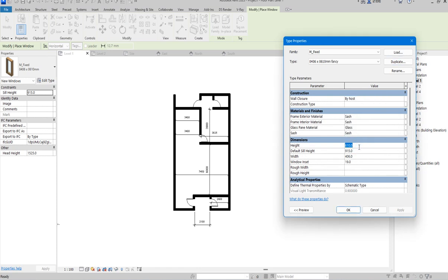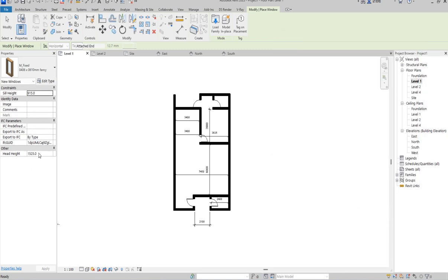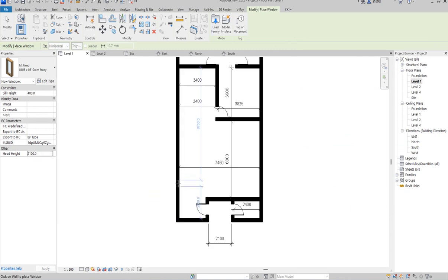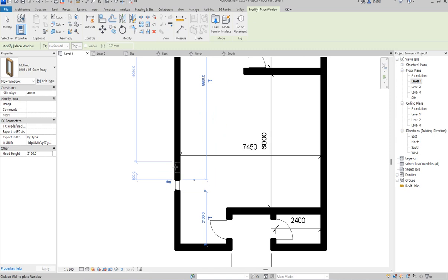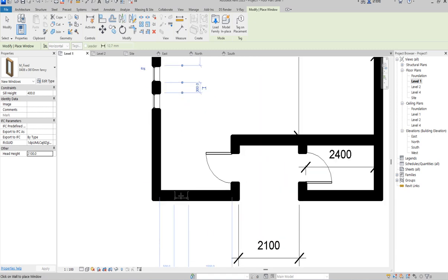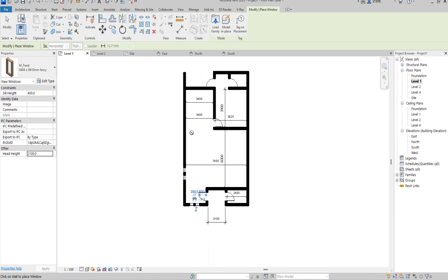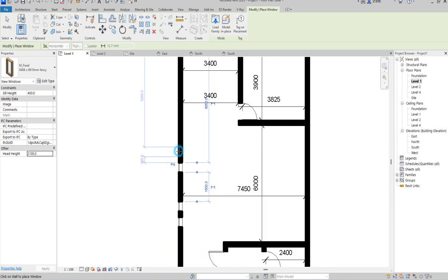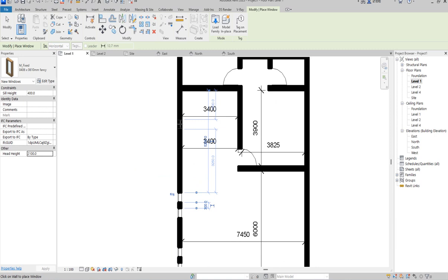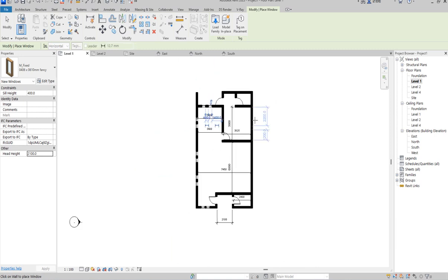So here you click on the height. I'm going to change the height to 1700. The width I will maintain at 500 for that. I will say okay. So change it from here, change it to 2100. So for the height, you can have as many as possible. So let it just be in place like that. Good. So we are still in the same process, so anything can still change during the elevation, but you just want to get the plan right so that we proceed from here. So this is it. Now we are done with that.